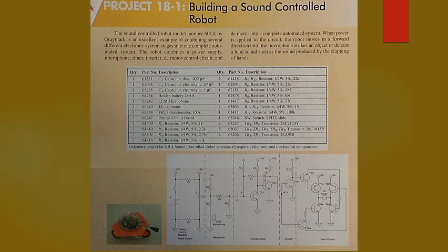They have, for example, the common base CB configuration, common emitter CE configuration, common collector CC configuration. You should understand what those are and what the differences are between them, what their purposes are for different configurations. You should understand different classes of amplifiers, class A, B, and C.